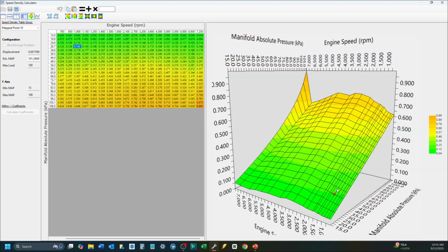It shows the load pressure, or the manifold pressure, and the RPM, and it gives a volumetric efficiency number, right? You can see here it goes from 0% up to 100% volumetric efficiency theoretically. And for each and every one of these conditions, there's an intersecting node, and you can even see over on the table as I move through this, the volumetric efficiency value that it's giving, right? And where I know VE, I know fuel.